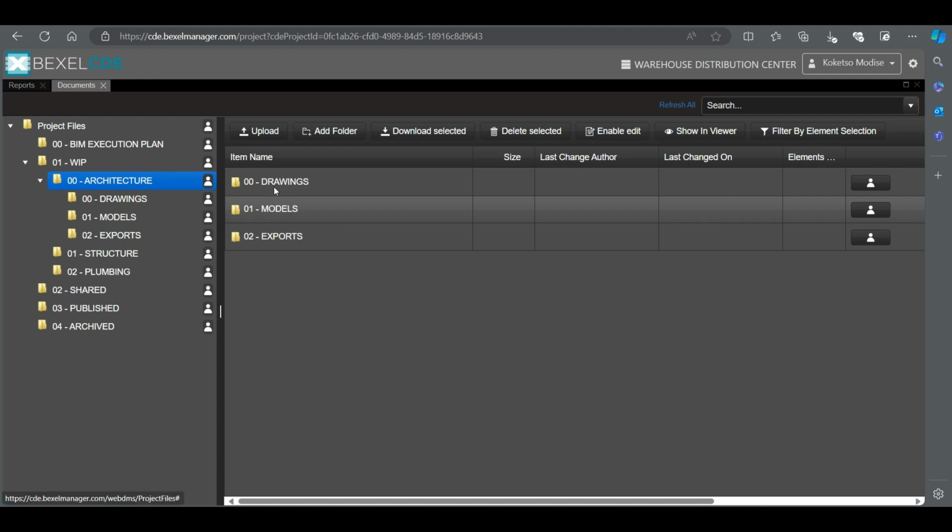They can be from Revit or ArchiCAD or Civil 3D and Bentley or other 3D modeling software. And your exports are basically the exportation of your 3D models, such as IFC, Industry Foundation Classes, and also your Navisworks models, which are NWC or NWD, which you can use for interoperability or information models, which you can use for different sets of BIM uses or your BIM goals, such as cost estimation and also your planning. So this is where they will be stored.